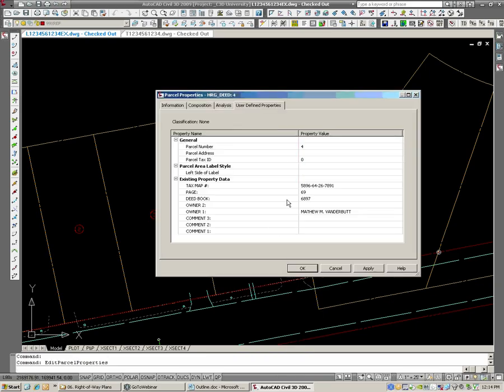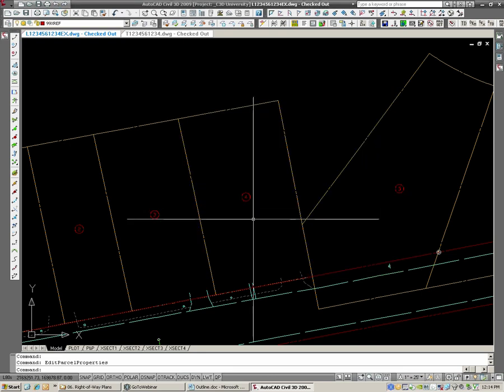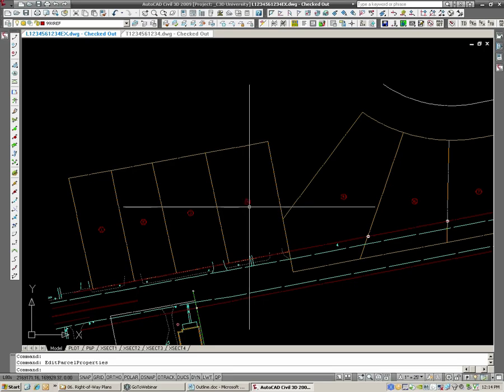So this is almost a little bit of a combination between GIS and AutoCAD's world, where with parcels you can enter in user-defined information. You could add any kind of information you want in here, as many rows and columns as we desire. So if there's more information that's needed for a right-of-way take plan, that can be added to this as well. But that information's added by our survey group, so that's good. It's already there. So we're essentially done with this file.